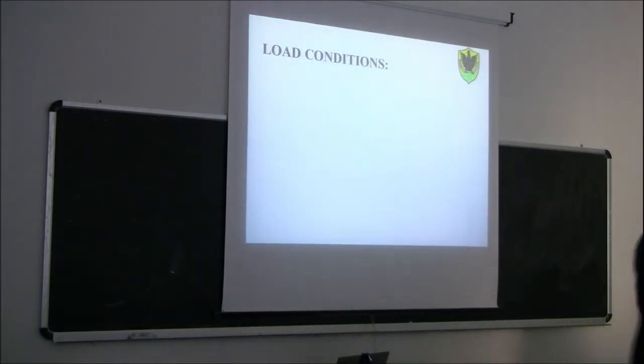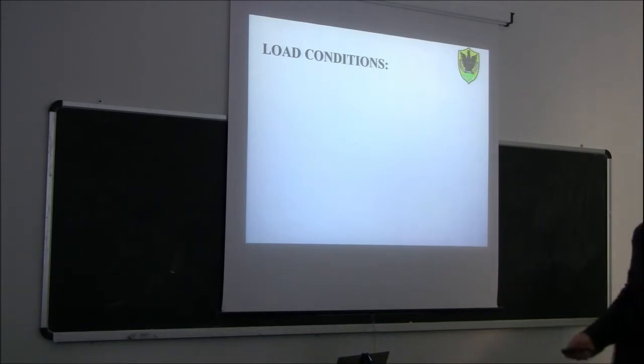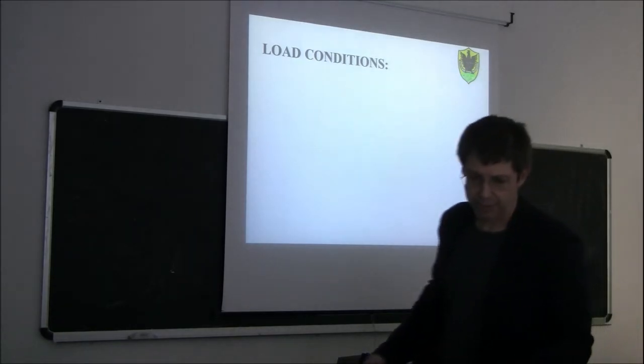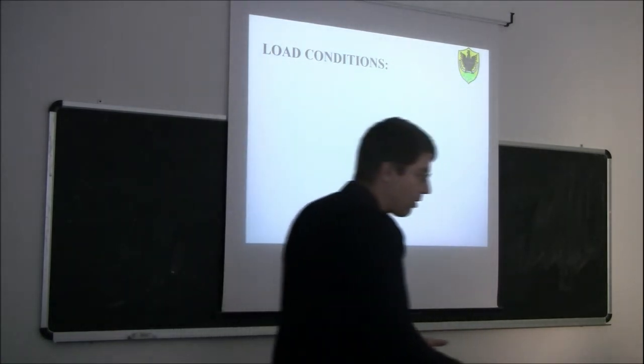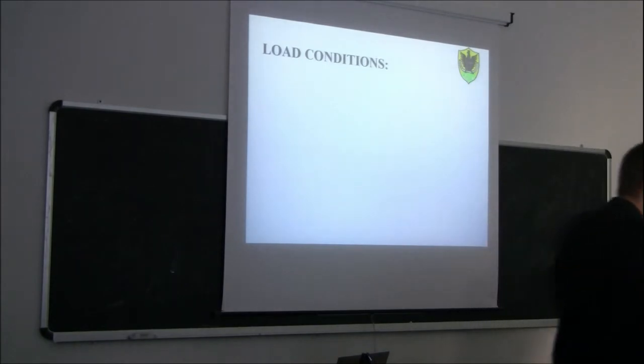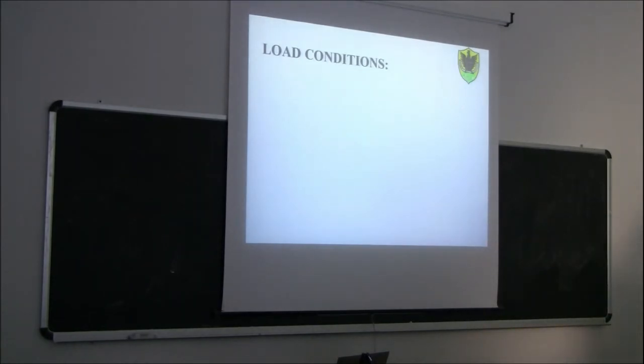In the next exercise talking about the roof, we are going to do the whole complete load assessment, and in addition to the snow, we are going to calculate also the maintenance and the wind. But I can tell you that in 90% of the cases, if we ignore earthquake, the snow load is by far the most important one when we talk about the roof.